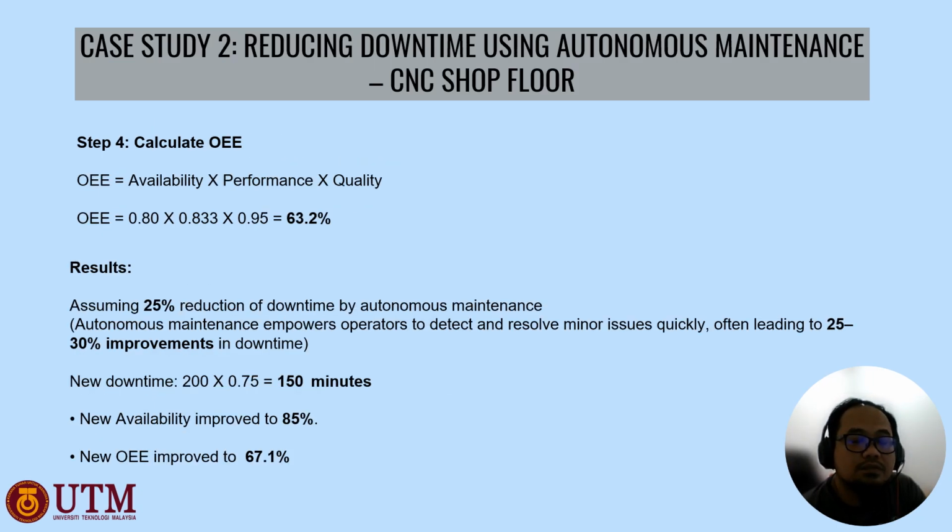And then the last, step four, we calculate the OEE. As we know, the formula of the OEE is availability times performance times quality. We have all these values, so we just put them in. The OEE from this case study will be 63.2%.